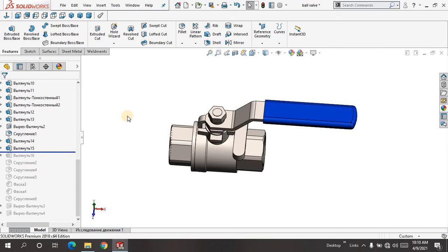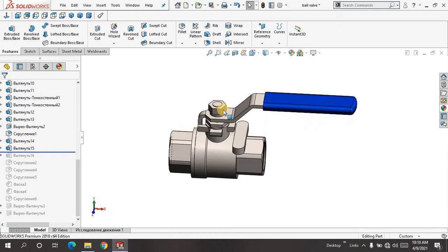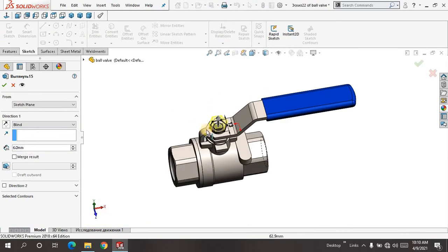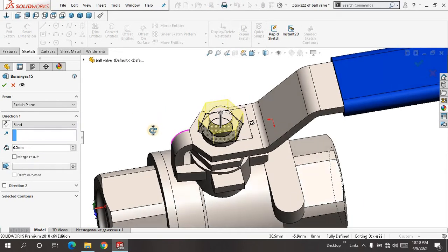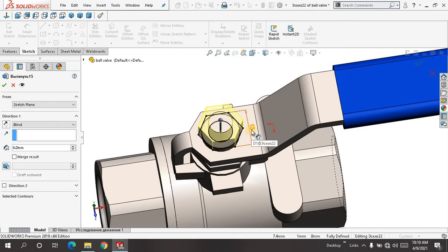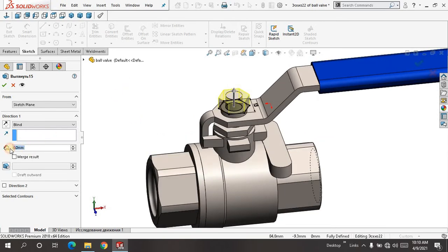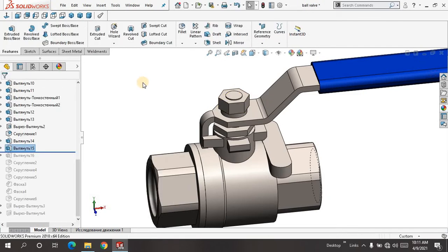Next, what I did, I just drew a nut and added a nut on the top of this. Let's have a look at the dimension of this nut. I just draw a hexagon over here, assigning the dimension to 2 mm, and having extrusion of 6 mm. If you want to change the extrusion length, you can change from here as well. If you want to keep it 7, you can. Let me keep it 6 for now. I will say okay.